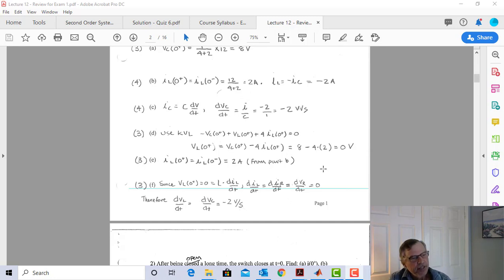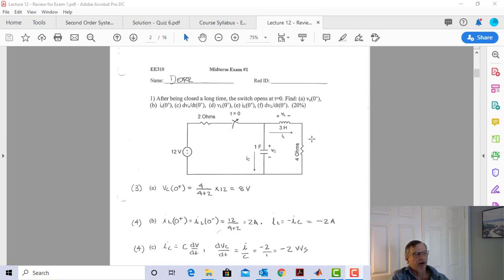So this was the tricky part, or the hard part of this problem, and I want to show you a little trick that helps me. When I have a horizontal component like this, what I'll do sometimes is, if I'm looking for the voltage across the component, I'll just say, what's the voltage on this side, and what's the voltage on this side, and then I'll subtract them.